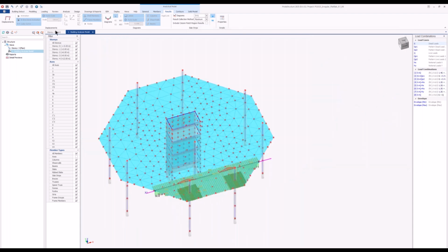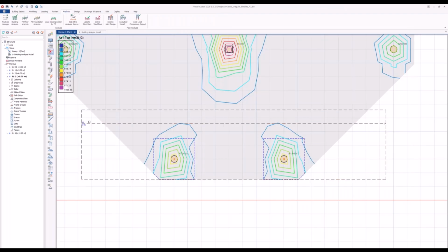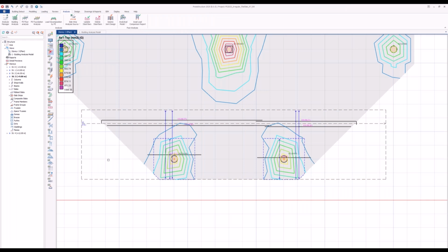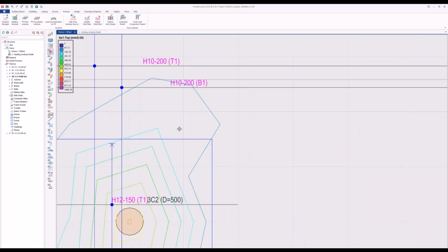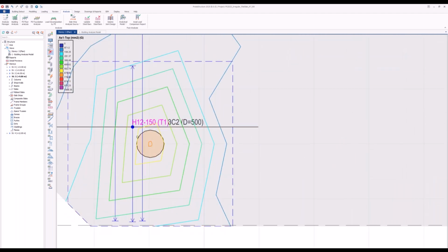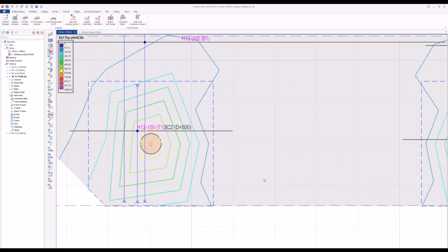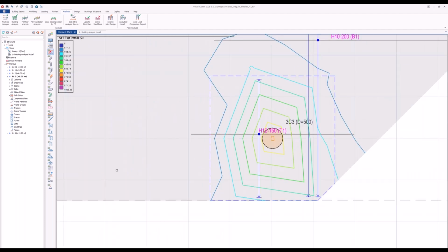Okay. Let's go back to plan view. Now I want to update the steel bars. Now, as you see, the base reinforcement dropped to number 10 at 200 millimeter spacing. And at the patch regions, we now started to calculate number 12 bars. So this is a way of calculating the additional top bars in the flat slabs. And if you are designing a mat foundation, we will start to calculate the additional bottom bars.